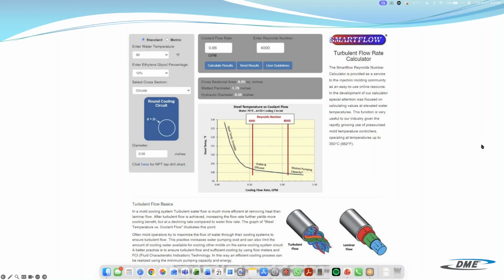But yes, you definitely want to have your water treated and maintained, because the other thing too is, if you're using a cooling tower and some of that water is being evacuated through air or steam or just natural, all that sediment and those minerals are going to stay in that water, so your concentration is going to get higher and it's going to eventually collect somewhere. So yes, I mean, treating your water is best, but it still has to be maintained as well.